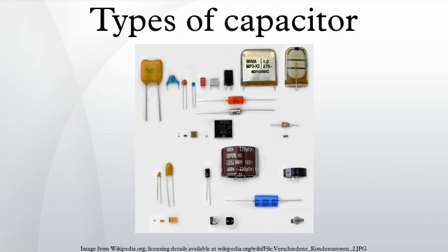Limiting current loads: a capacitor can act as an AC resistor, coupling AC voltage and AC current between two points. Every AC current flow through a capacitor generates heat inside the capacitor body. These dissipation power losses are caused by ESR and are the squared value of the effective current. The same power loss can be written with the dissipation factor.